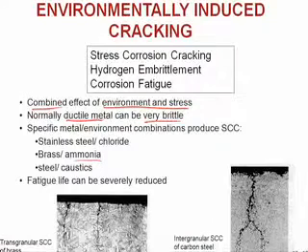Here's steel. Carbon steel can, under most circumstances, exhibit a lot of ductility. Here we have intergranular cracks, cracks along grain boundaries. And these can happen at stresses well below the yield stress. So again, these are stress regions where we would expect elastic behavior, not plastic deformation, not failure, low stresses, and yet we have cracks forming.